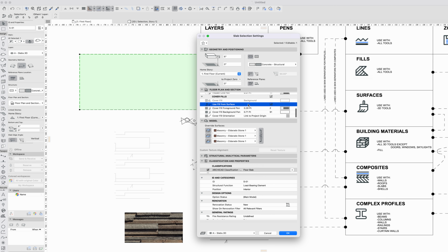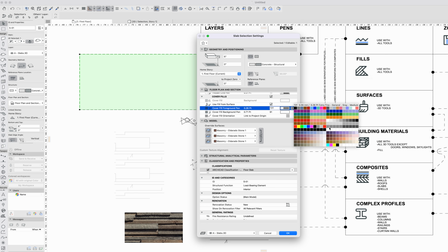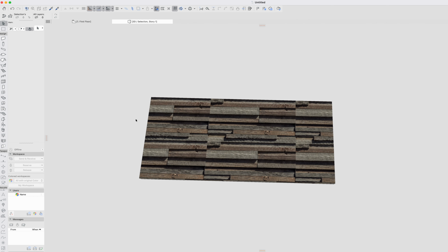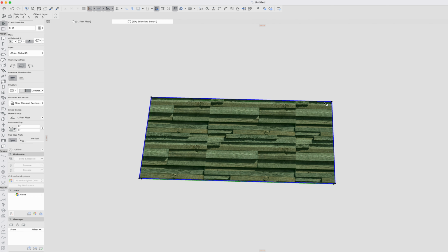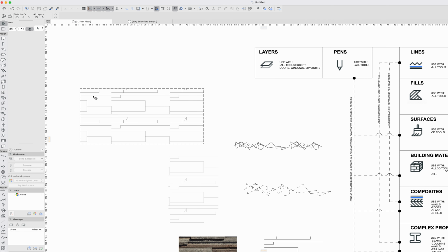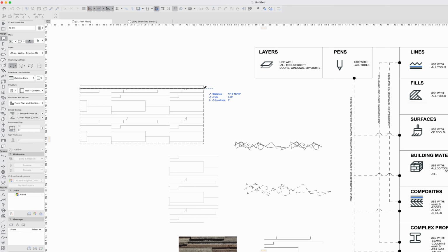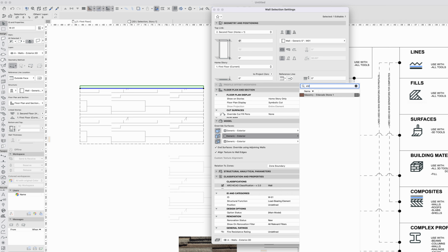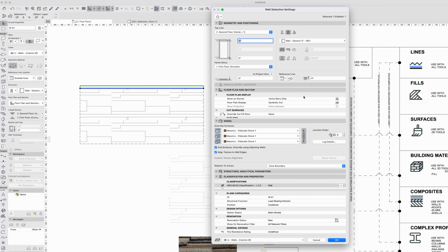We can then set the pens of that cover fill, right? We were using this in the surface settings. So slabs and roofs, when we apply a cover fill, are a little bit different than walls and things, but we do get that pattern, and that pattern, if we look here, is going to match that pattern. Anyway, if we look at this in terms of maybe there's a wall or something that this is probably more likely to get applied to, we'll drop a wall in here, and we'll apply surface overrides, and we'll put the Eldorado stone on that wall.